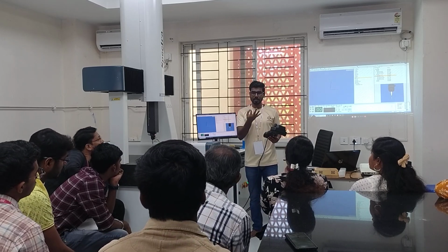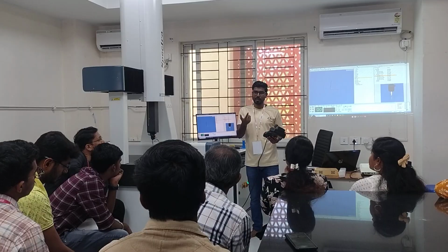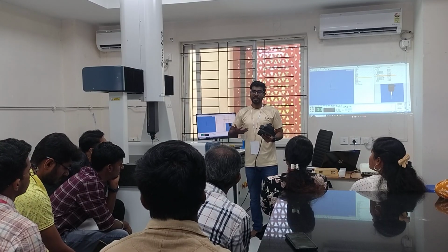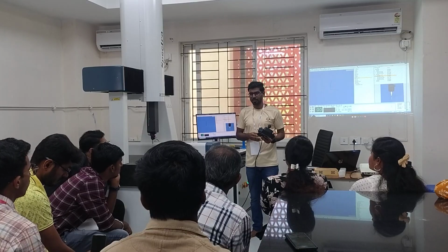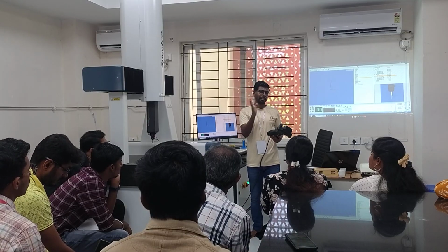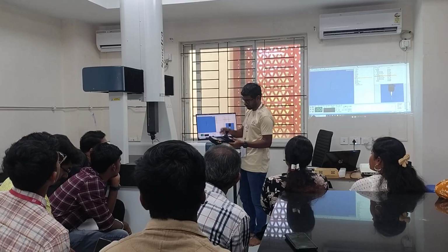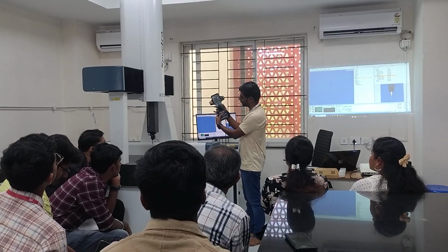If there are 3 points, what is the planarity? Will it be equal to 1, or might it deviate? Planarity or flatness, you can say flatness. If you are using 3 points, it will be totally, perfectly flat. So for this, I'll take more than 3. I'll take 5.